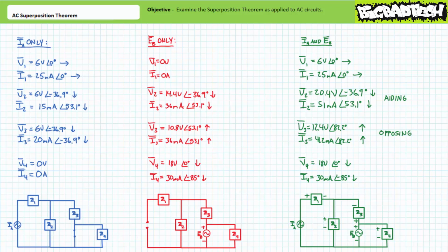Until then, let me remind you the superposition theorem isn't necessarily a new technique, but rather repetitive series parallel circuit analysis, a technique you've got ample experience with by now. Very often, it isn't necessarily the electrical concepts, but rather organizing the results of the independent analyses and accounting for magnitude, phase shift, polarity, and direction that trips students up when employing superposition theorem for the first time. Current with a wrong direction or voltage with a wrong polarity or failing to take into account phase shift can have disastrous consequences. Take your time and stay organized when summating results. Pick a direction and just stick with it.